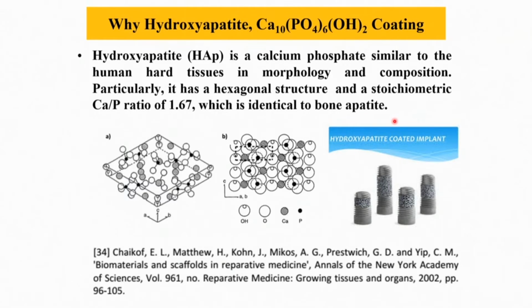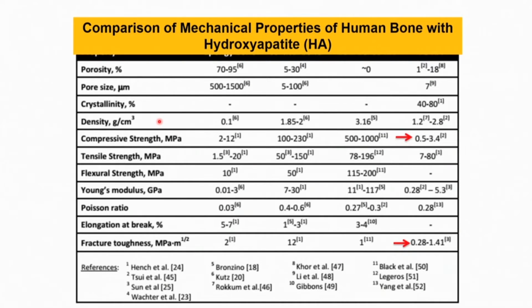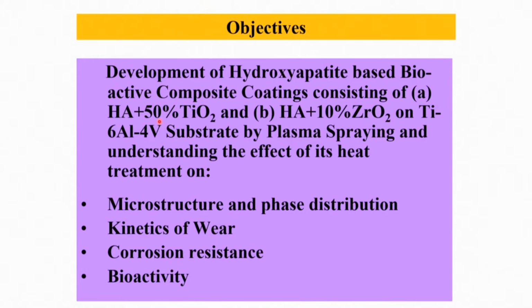So, this is a typical hydroxyapatite coating which is very much bioactive in nature. Usually it is applied on the implant by the dipping technique, as I mentioned. That hydroxyapatite has a calcium to phosphorus ratio of 1.67, which is the indication that the hydroxyapatite layer has formed. It has very good corrosion resistance and very good fracture toughness, porosities are also present which help in cell adherence, and moreover this is bioactive in nature.